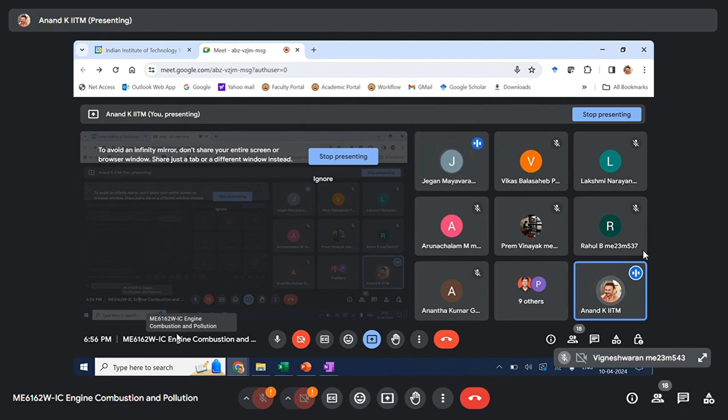Okay, so it means the turbocharger is clean because you are not letting any exhaust gas go into the turbocharger. Not turbocharger, I'm sorry, the compressor. Yes, the turbocharger handles exhaust gas, compressor handles air. When you mix air and EGR at inlet to the compressor, the compressor is handling a mixture of air and exhaust gas. This is called low pressure EGR loop. The other option is you mix EGR, that is exhaust gas, with air at the exit from the compressor. That is called high pressure loop because the air leaving the compressor is at high pressure.